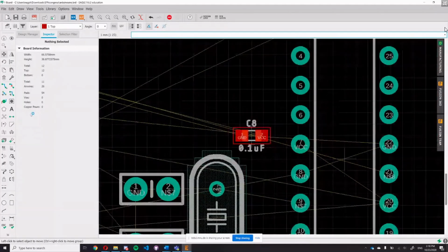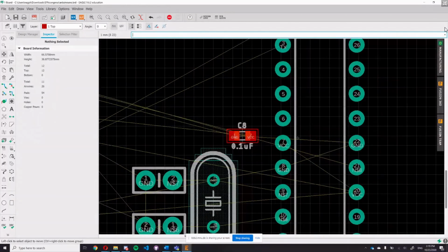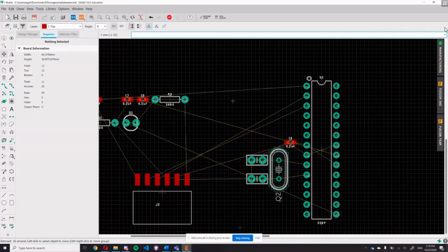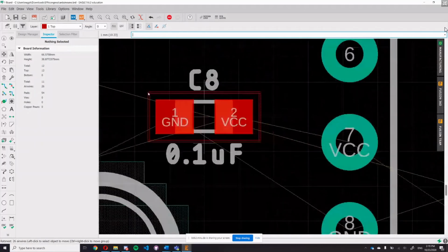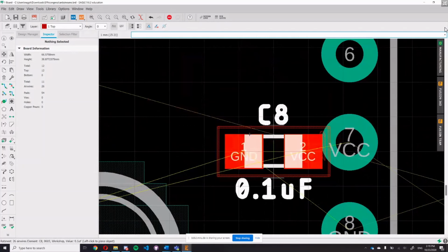So what you can do when you have something like this, you can look for a tool called RatNest. What this does, if we zoom out, is find the shortest direct path between the two points that need to be connected, and it just redraws the yellow line. So if I click that, you can see that they reorganize. And now the VCC is going directly to this pin.